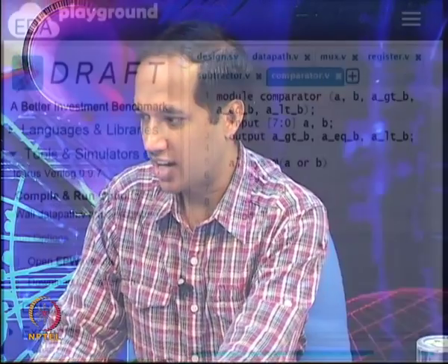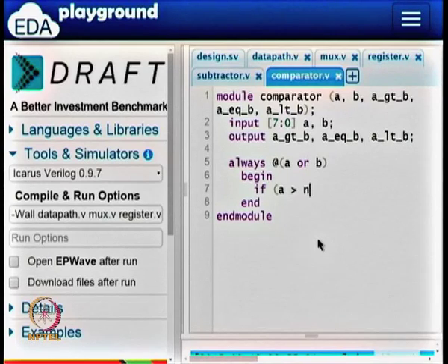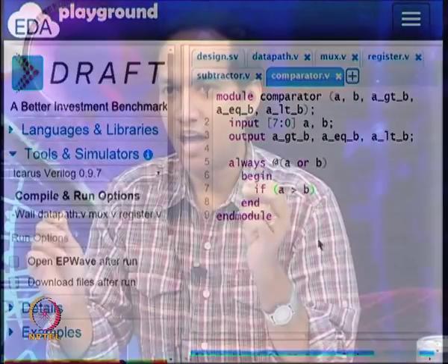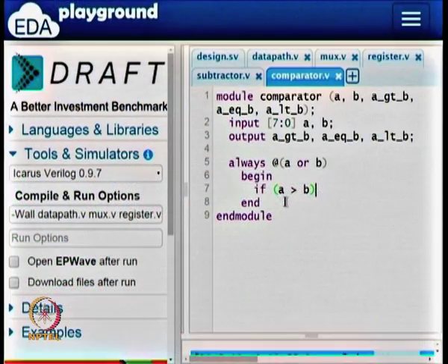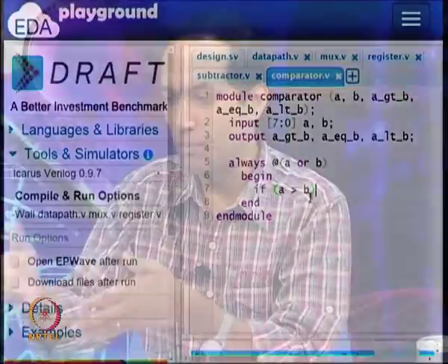So I am going to check if A greater than B. This is just like what you do in programming languages. So instead of comparing them bitwise, I am letting Verilog use the comparator operator. A and B are interpreted as 8-bit values, and the 8-bit interpretations of A and B are used directly. When the simulator runs, this greater than is a simple operation: you take the 8-bit value and compare with the 8-bit value. But later when we want to infer a circuit for this, the synthesizer will look at A greater than B and generate an appropriate circuit.